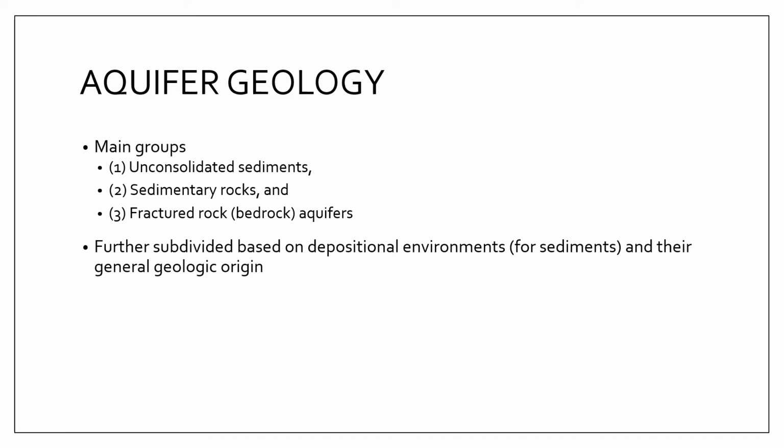We also have sedimentary rocks, which is chiefly comprised of sandstone and other types of sedimentary rocks. And finally, you have your fractured rock or your bedrock aquifers, which are all about aquifers that rely on your secondary porosity. So these are the aquifers that rely on fractures, joints, and faults and foliation as well for them to have an ability to transmit groundwater,